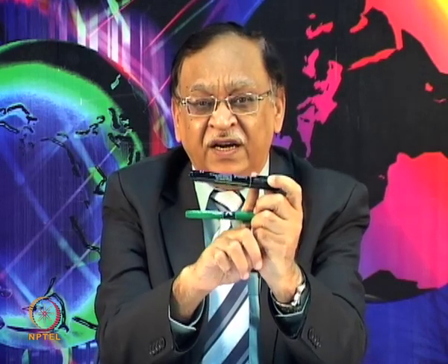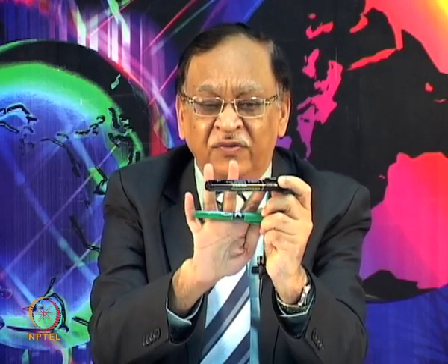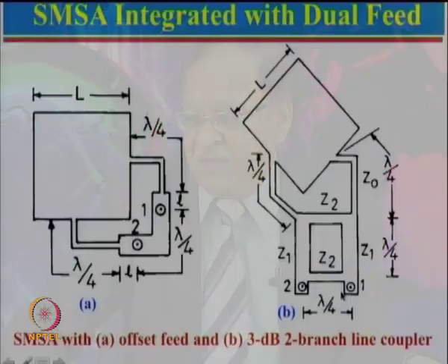to some other circuit. Now, that is a coupled line, but for circularly polarized antenna what do we need? We need output which has equal amplitude. So, this is not going to do the job. So, to increase the coupling, instead of having a gap between the two, if we now physically connect a line like this and physically connect a line like this, what we have achieved is two branches which are going from here to here and over here to here. That is what the configuration is known as.